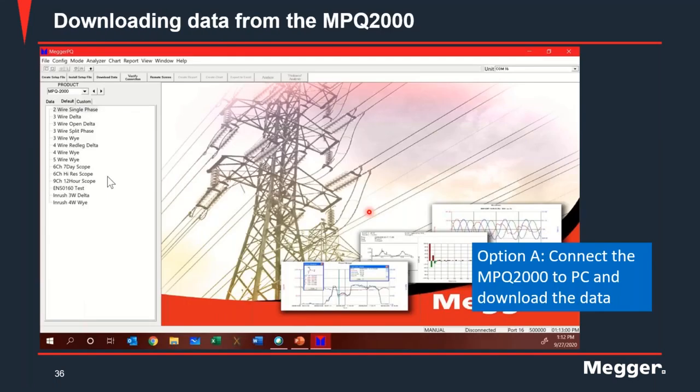Once the MPQ2000 has recorded the data, you can get the data off of the unit and transfer it into your laptop. There are two ways of doing it. Either do it directly by connecting your unit to your laptop. So this is option A, where you are downloading data directly from the recorder to your laptop. You can do that by clicking on Analyzer and then selecting Retrieve, or you can click on Download Data, which is the third step that's provided over there.